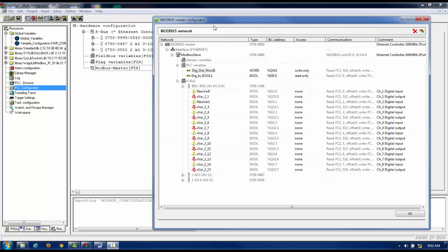So now you can see we're back in the Modbus Master Configurator tool, and here I'm referencing again the registers and coil values, bit values for the slave device. But let's not assume this is always going to be a coupler. Perhaps this is a controller, and having direct write access, for example, to these registers may not be allowed. So what I may need to do is put information into a register that I do have write access to. So I'm going to show you a couple things here.